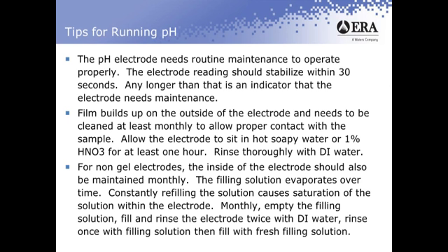Then what I'd recommend is taking a deionized water bottle and filling up the inside of that electrode with deionized water. Again, shake it out, similar to the way you shake a hospital thermometer. Rinse that through a second time. What that does is ensure that the electrode is cleaned out of the filling solution that's in there. Once you do that, you also want to rinse out the deionized water that you've now put in there.